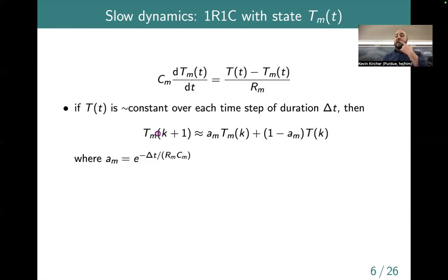Okay, and then if we look at, again, maybe we're doing long, slow simulations, we care a lot about what's happening with the mass temperature. We can basically assume away the time derivative, assume that the indoor temperature is constant. And then we get basically just this one equation. And this actually is literally directly transcribing the second equation that showed up in the original governing equation system.